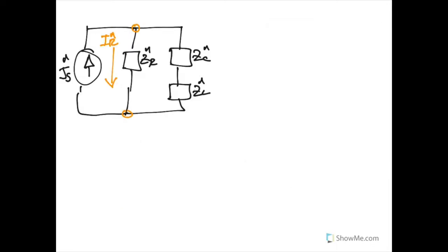In the previous problem, we found the current passing through the resistor, and we did that because our overall goal was to find this voltage out here, the voltage across basically the entire circuit, and the voltage supply. And so to do that, we wanted to know that this voltage right here is equivalent to the current flowing through the resistor times the impedance of the resistor itself.